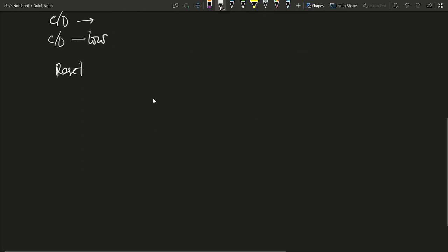So now we talk about the transmitter part. Each block maintains its own working function. First point, the transmitter section accepts parallel data from the 8085 and converts it to serial data. Second point, the transmitter section is double buffered, that is, it has a buffer register to hold 8-bit parallel data and another register called the output register to convert the parallel data into serial bits. Number 3, when the output register is empty, the data is transferred from the buffer to the output register.